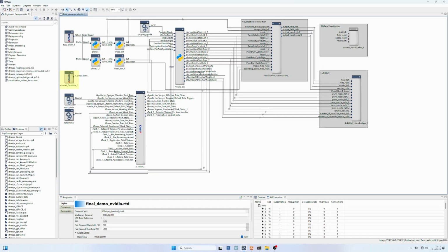The first component is the control function. With it, we can configure the CAN channel and the control function parameters. Using the TECU client, the application communicates with the tractor ECU. This way, it provides the actual speed. Processing of additional values is also possible, but not needed for our use case.